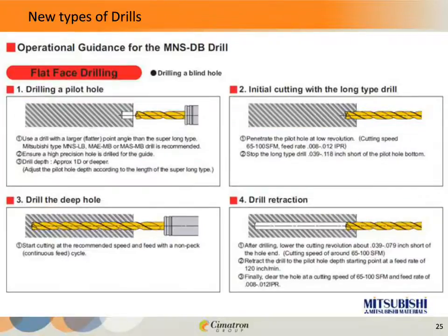Okay, next we're going to look at the different operations. So we're coming in on a flat face. Again, speaking in generalities, probably if the diameter to length ratio is less than 5, maybe we don't need a center drill or a pilot, but depending on the application, if the drill requires a deep hole, probably we're going to be at least drilling the pilot hole.